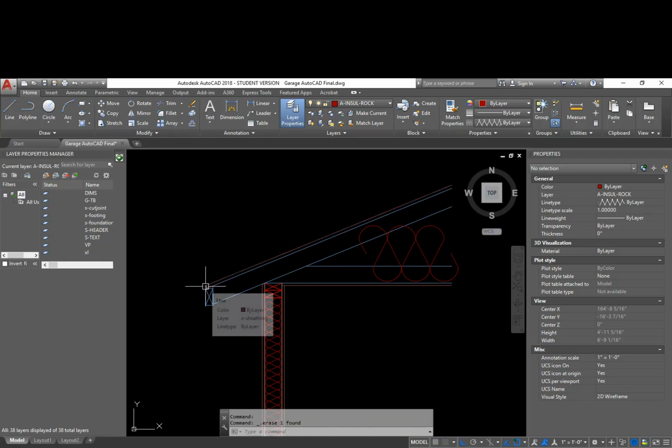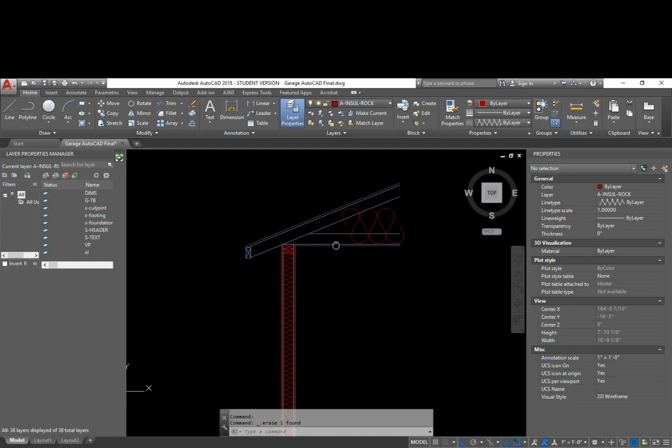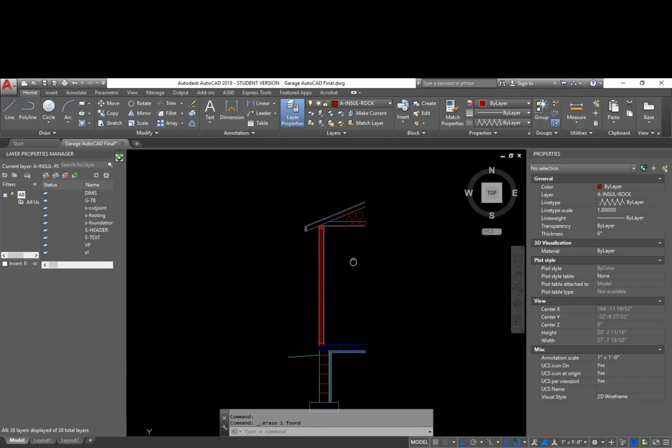The water refreezes here and starts to make icicles, and it starts to work its way back up through. It wicks its way, and a lot of times it'll find its way into this wall cavity and slowly rots that wall without anyone knowing it. So you don't want to block that airflow, so I don't want to stuff this insulation in there. There's a couple different things that we could do. I could just reduce the amount of insulation out here, which isn't the best option.